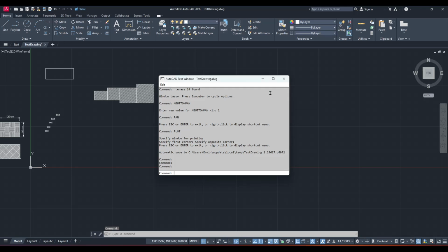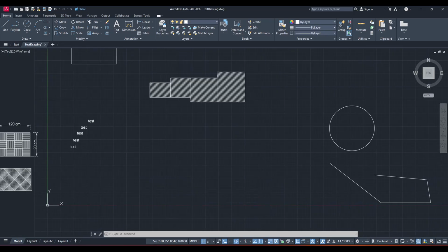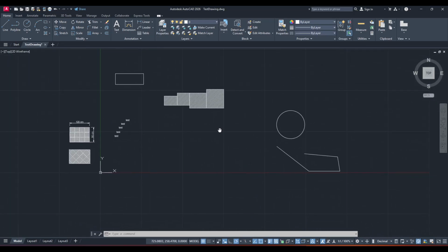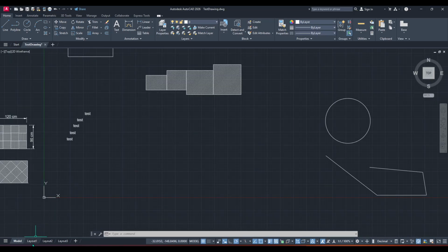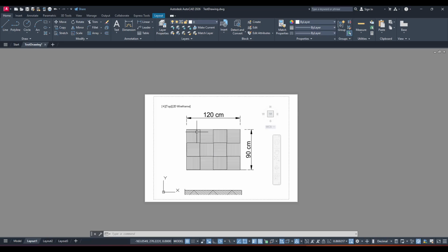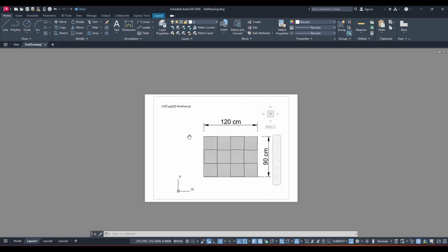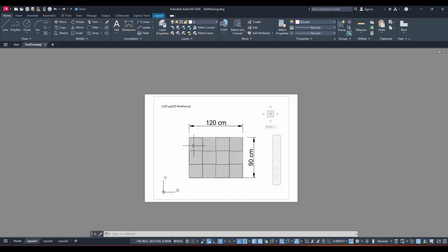In today's video, I'm going to teach you how to exit from AutoCAD Viewport. If you've ever found yourself stuck panning around inside a layout viewport when you actually want to select notes, borders, or title block elements, this is exactly what you need. The goal is simple. Switch from editing the model through the viewport to working on the sheet itself in paper space. Before we begin, a quick refresher.